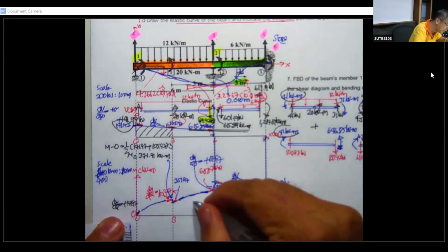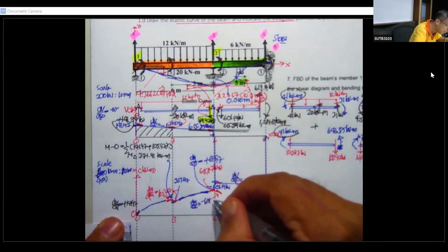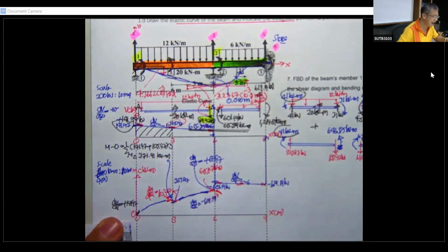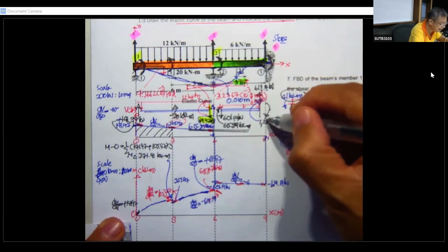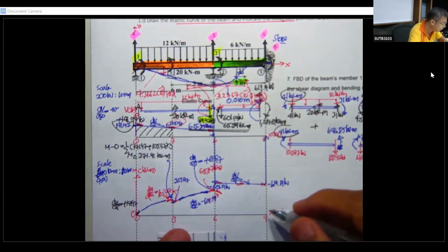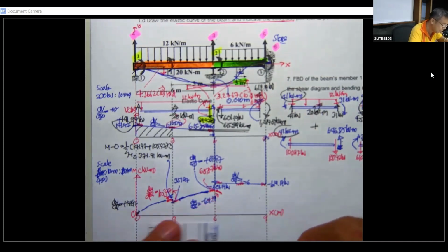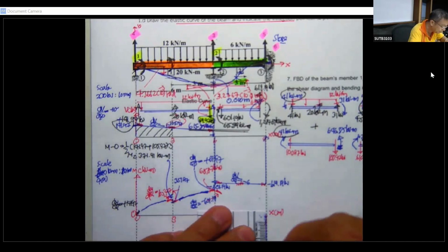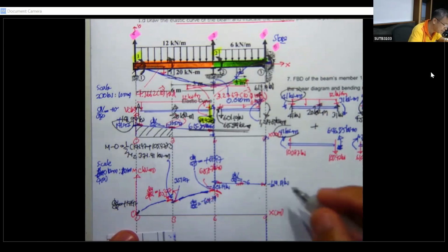The shear dM by dx is going to be minus 601.19, and then due to this one, the M here is going to be negative, so it's negative for 3 centimeters something, okay, it's going to be negative over here, minus 1214.69, and then you have this one for 619.19. So the slope here is very high.